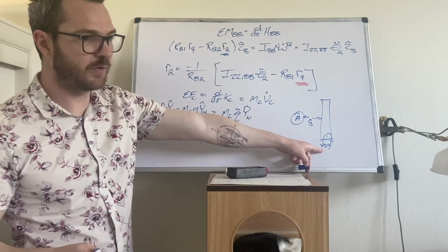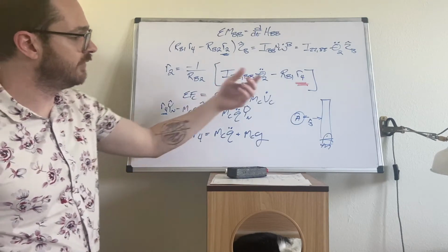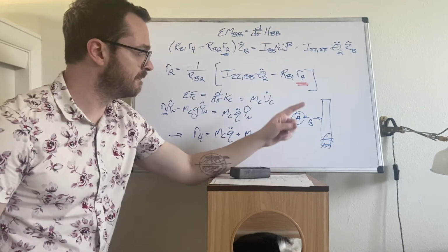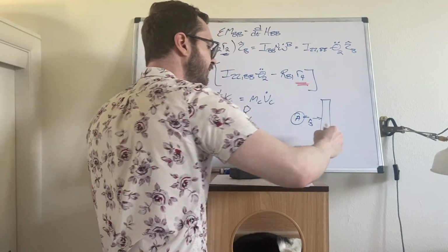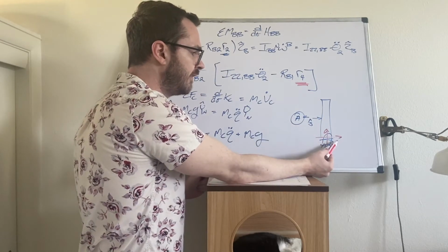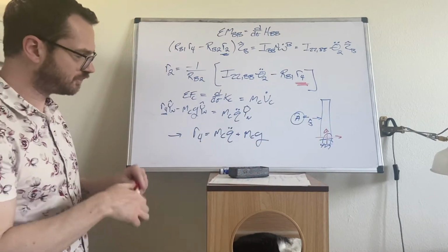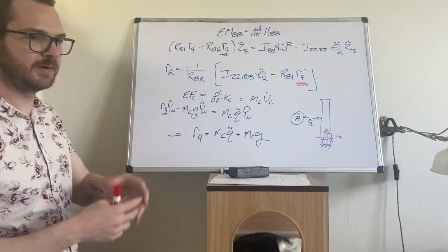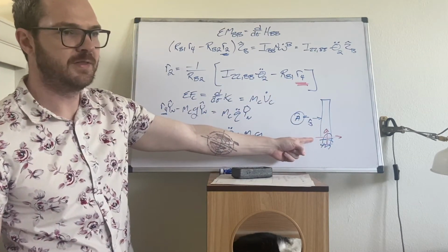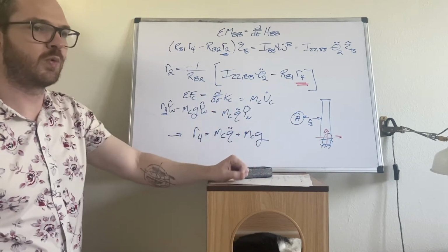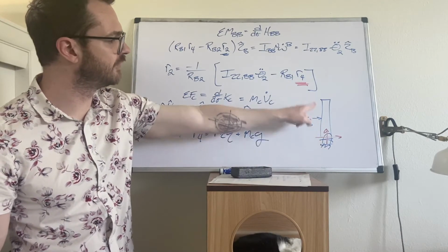We need to go look at the equations for body D. Which of the equations should we look at? If we do the sum of forces on body D, then the reaction forces at the pin joint are going to come along, and we don't have expressions for those. So we would simply be solving for R5 in terms of, again, an unknown reaction force. That leaves sum of moments. I want a sum of moments, an Euler's second law equation for the pendulum, that does not involve these reaction forces, which is, of course, why earlier I defined the moments on the pendulum about the pin joint, such that those reaction forces are not in the equation.